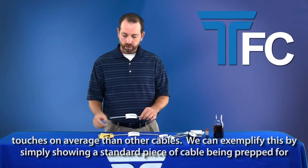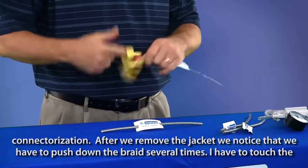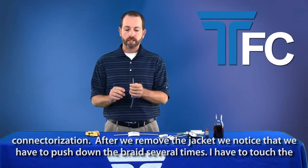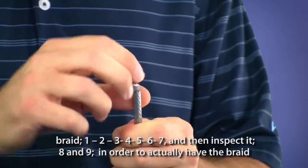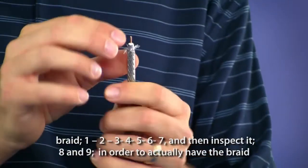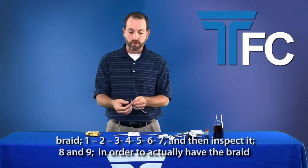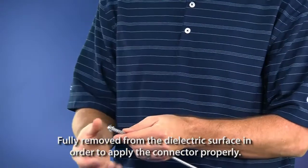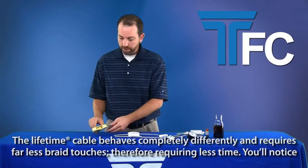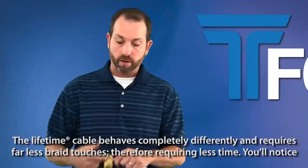We can exemplify this by simply showing a standard piece of cable being prepped for connectorization. After we remove the jacket, we notice that we have to push down the braid several times. I have to touch the braid 1, 2, 3, 4, 5, 6, 7, and then inspect it, 8, and 9, in order to actually have the braid fully removed from the dielectric surface or the foil surface in order to apply the connector properly. The lifetime cable behaves completely differently and requires far less braid touches, therefore requiring less time.